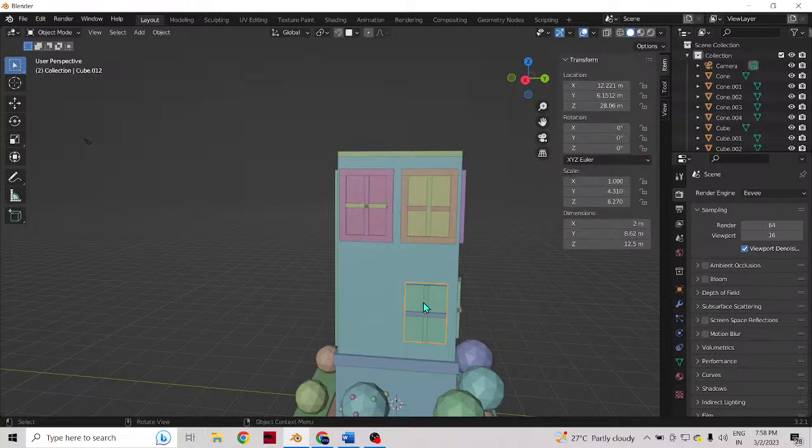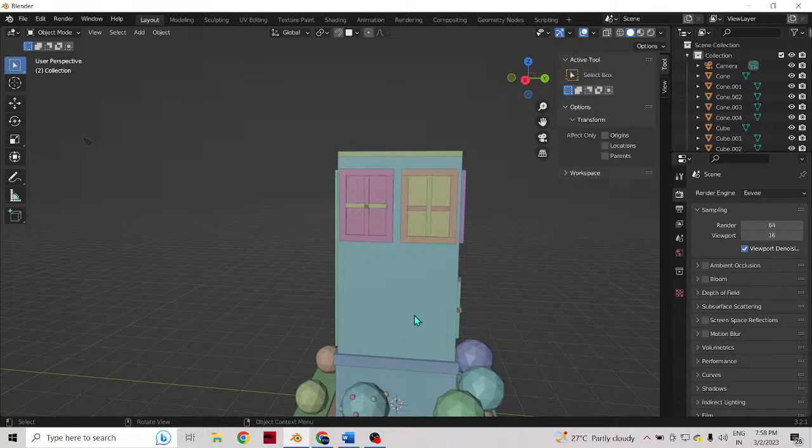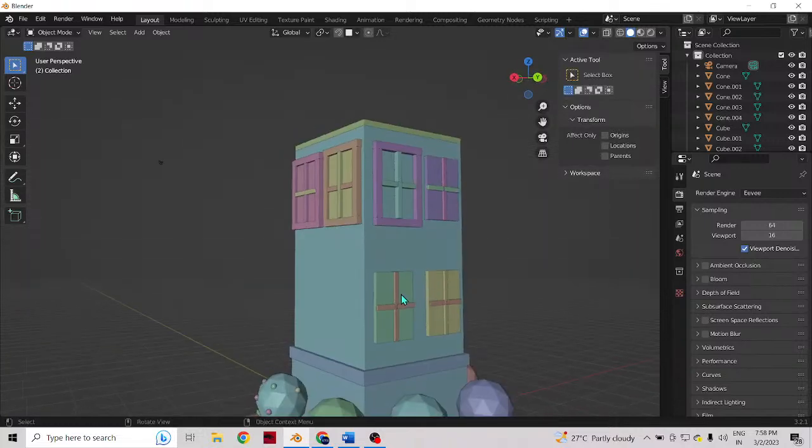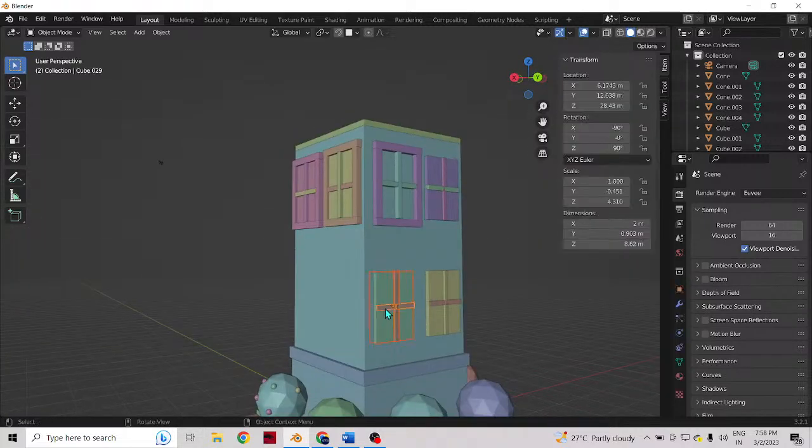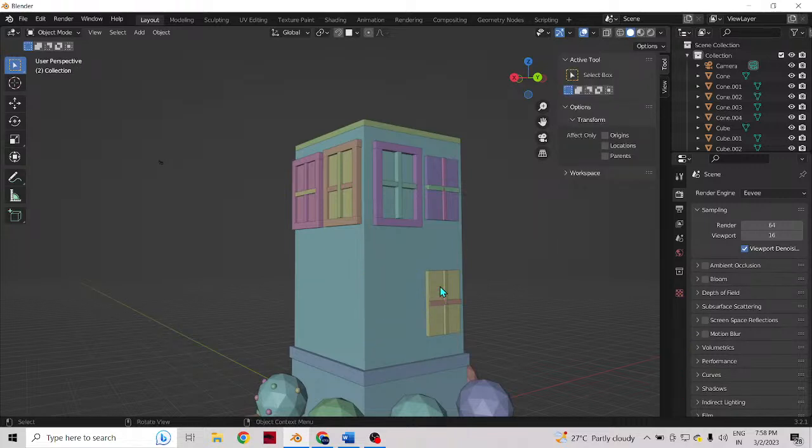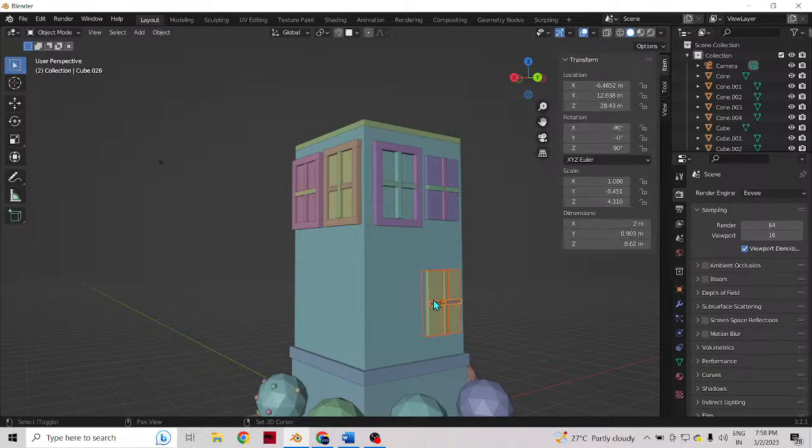To delete an object, here we have Kasi who has answered that a cube has 6 faces. Good. So to delete an object, we have to select the objects and then hit X on your keyboard. Once you hit X, you will get this option, delete. If you give OK, it will be deleted. The same way, I'm just going to delete all these things, X and delete. Then again I'm going to select this, X delete. Here again I'm going to select this, X delete.